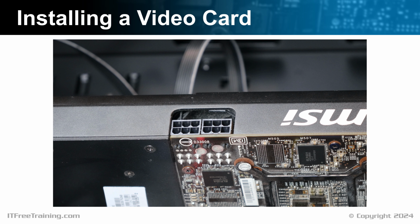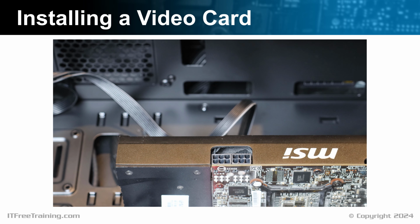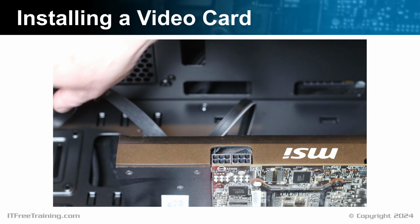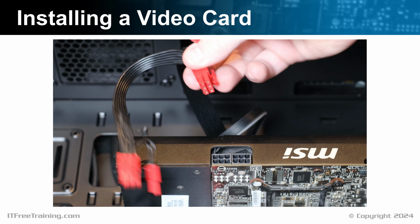Your power supply should have a PCI Express power plug unless it is really old. This power supply has a 6-pin power plug which can be changed to an 8-pin. The extra pins provide more power. Different video cards have different power needs, and this will determine which connectors you will use. I will next plug in the 2 PCI power plugs. Once these are plugged in, the video card hardware installation is complete.